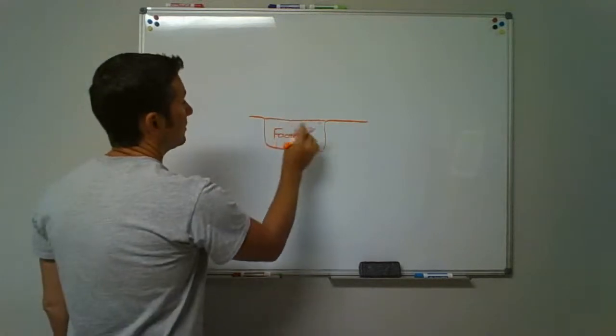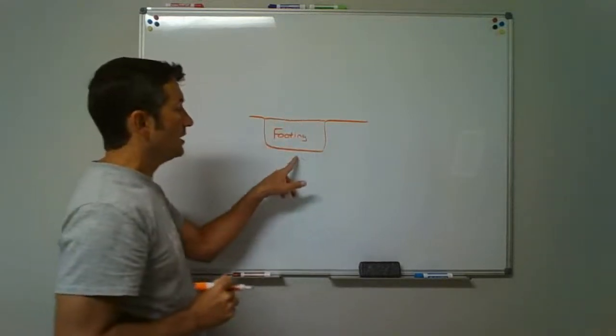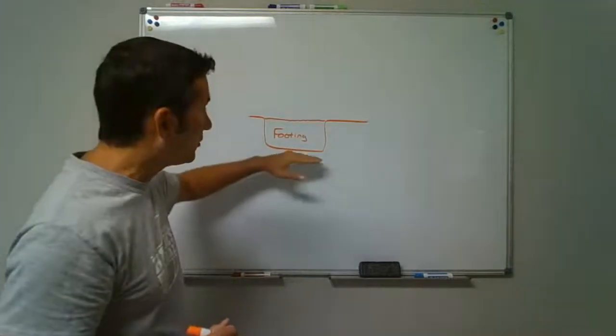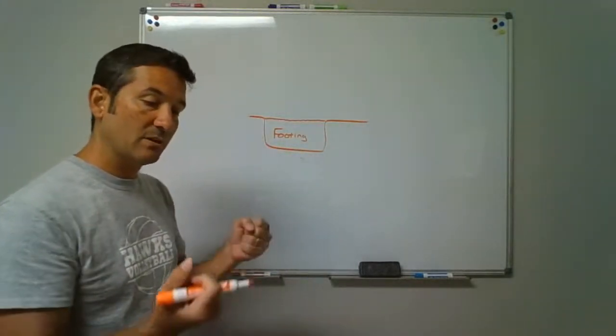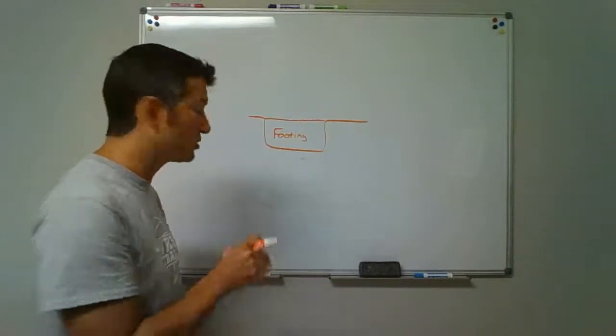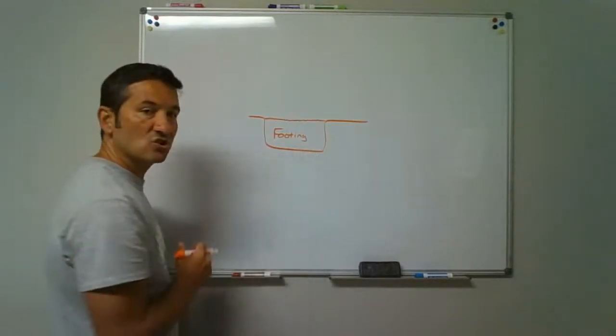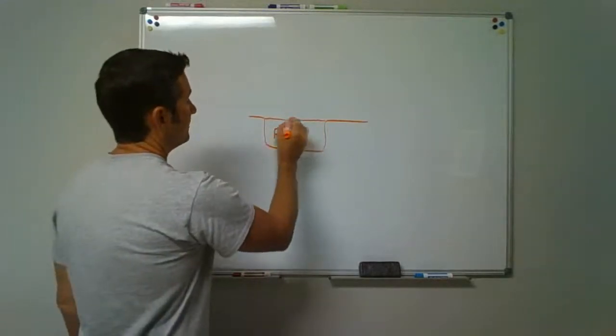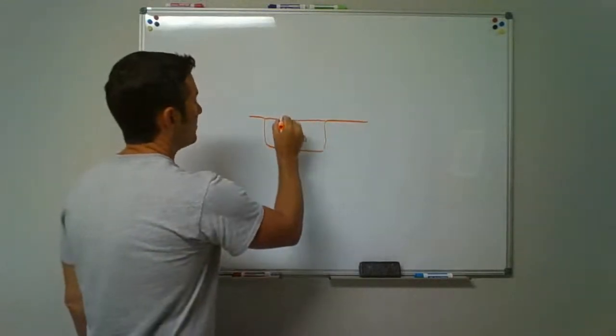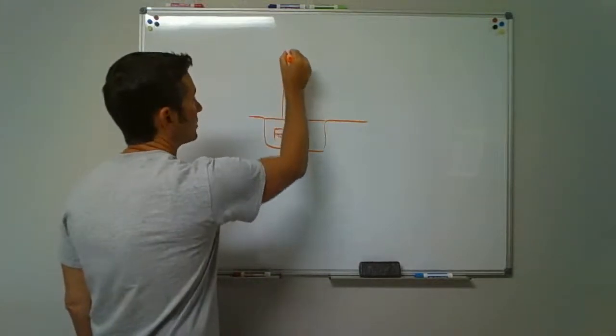They get the ground underneath inspected. An inspector might come with a compression rod, push down, and make sure this is good solid ground that the footer is poured on. This concrete footing all the way around gets poured, and that's what they build their walls up on.